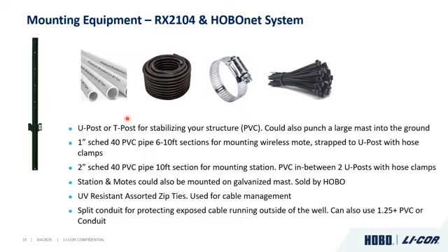When it comes to the moats, they're very small and lightweight. You can use 1-inch PVC. But when it comes to the station, you'd want to at least use 2-inch PVC pipe. And you'd also, on those stations, probably want to use at least 2 heavy-duty T-posts to kind of secure your station, especially when you're building a large wireless network of sensors. Everything's going to that one hub. You want to make sure it's protected in a sturdy structure.